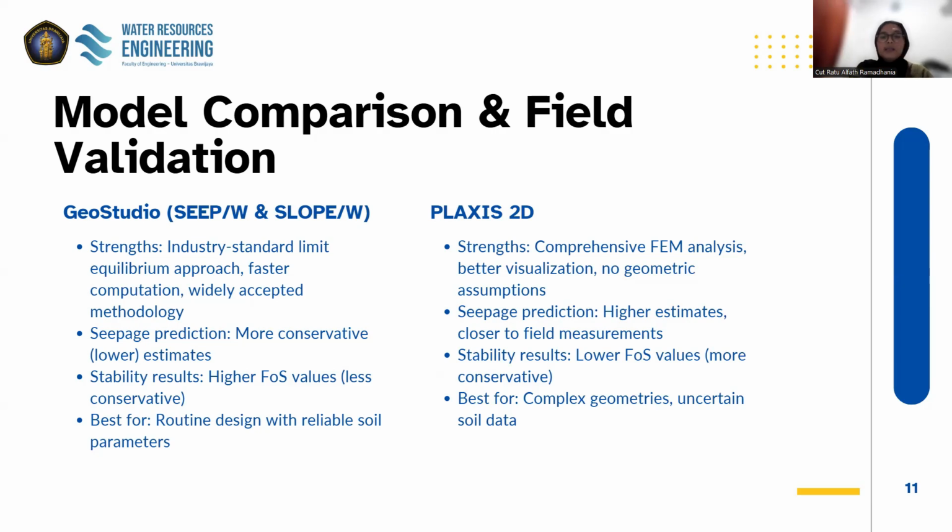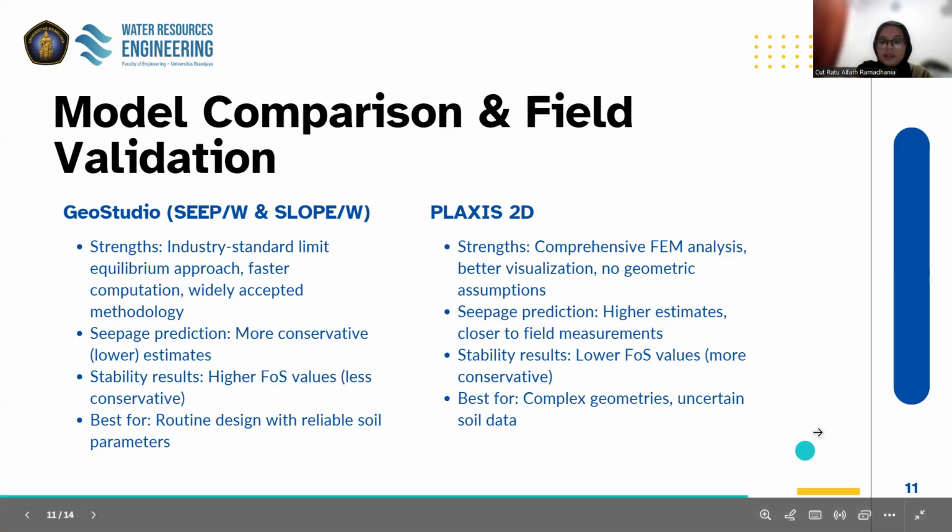And for the Plaxis models, the strengths of Plaxis is comprehensive finite element method analysis, better visualization and no geometric assumptions. And for the seepage predictions, Plaxis is higher estimated, closer to field measurements. And for the stability results, the Plaxis one has lower safety factor values, so it is more conservative. And the Plaxis one is best for complex geometries and uncertain soil data.